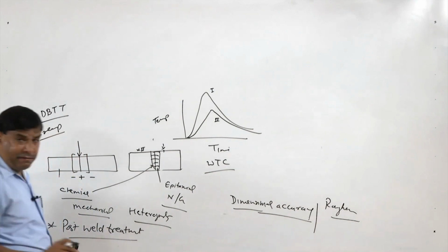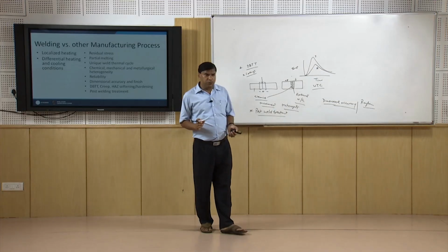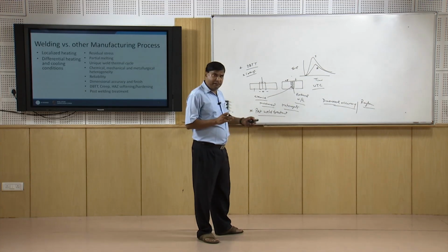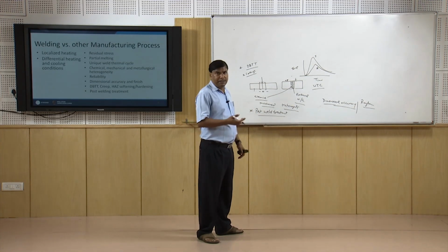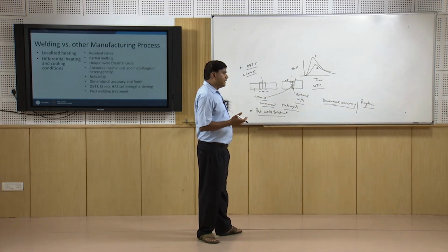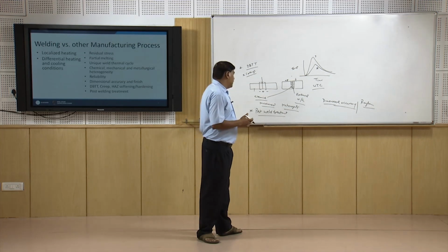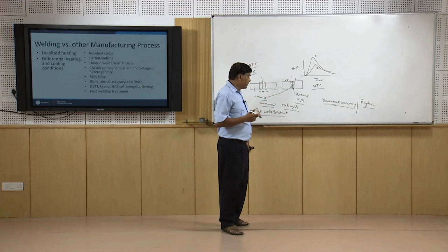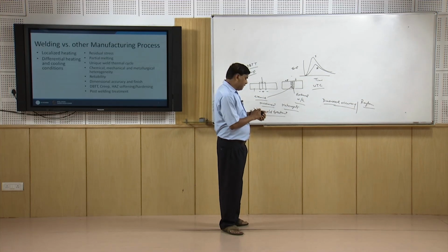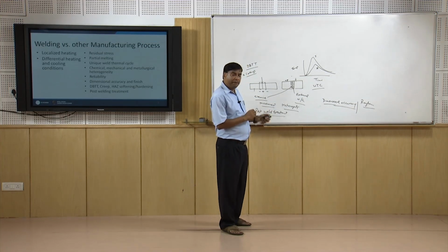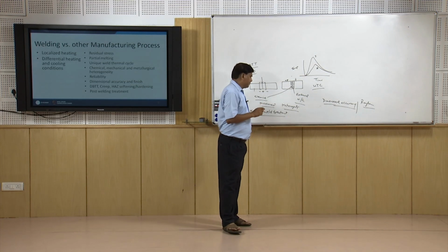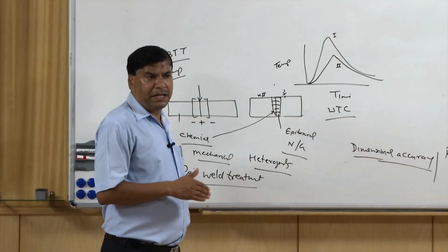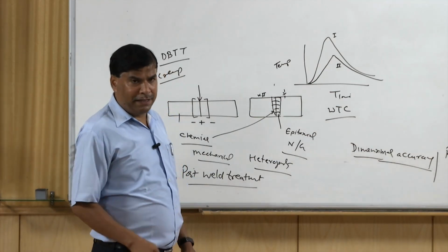Welded joints frequently develop residual stresses. So, to neutralize the residual stresses developed during welding, sometimes post weld heat treatment is performed or shot blasting is carried out, which will improve the fatigue resistance as well as induce compressive residual stresses. So, for critical applications, sometimes post weld heat treatment or shot peening or special treatments are carried out, so that the negative effect of the welding can be eliminated.